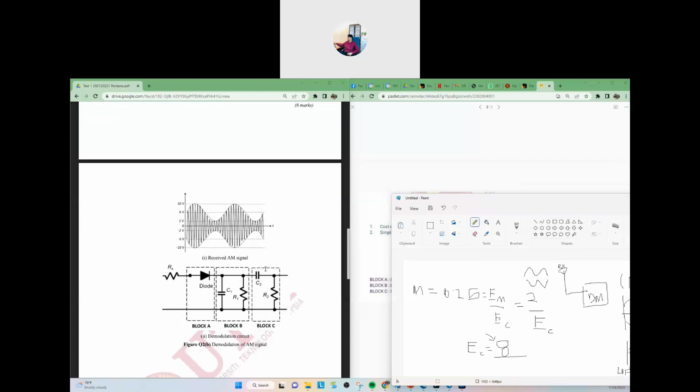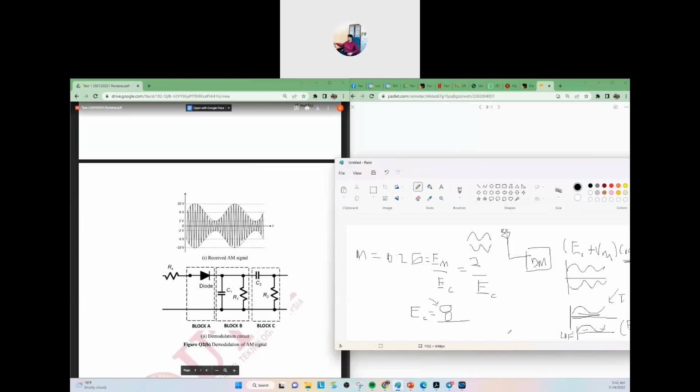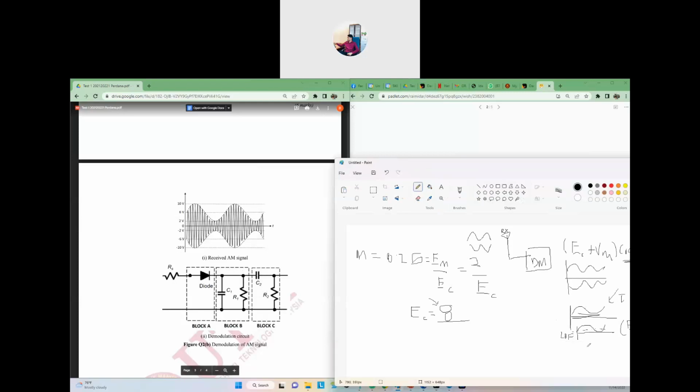here. The next stage is a DC blocker. What a DC blocker does is that it will remove the DC component, only retaining the alternating current. So in the end you will be able to get, this one is after the low pass filter, this one is after the DC blocker, so you receive your original signal again, although it can be small, but at least it is the same signal that we are trying to submit.